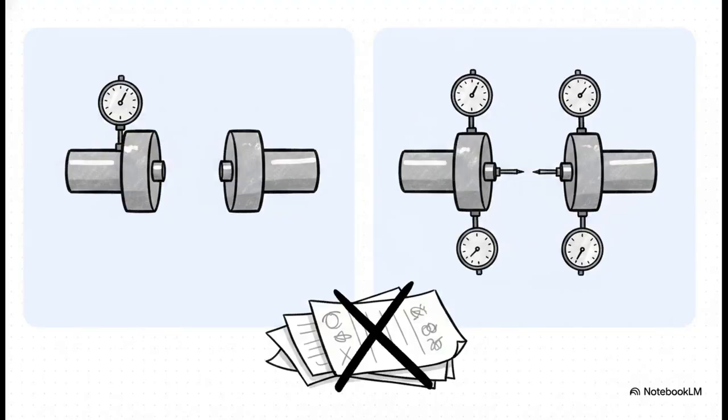So, depending on your machinery setup and the specific protocols at your plant, you might be using a couple of different alignment techniques. Now, whether your site requires the traditional rim face method, utilizing 4-point face and rim readings, or if you're using the reverse indicator method with rim-rim readings from both sides of the coupling, this app has you covered. It provides dedicated, highly accurate calculation modes for both of them, which essentially means you can finally stop carrying around different cheat sheets for different machines.